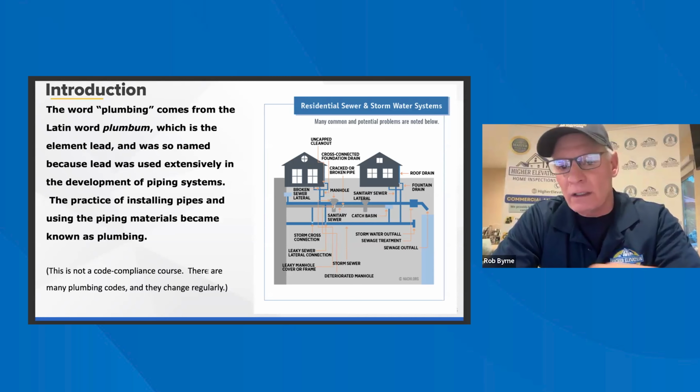And you can tell because one section is going to have air and the other section is going to have the water. You tap on it and you'll hear a distinct difference between the two. The expansion tank provides space for the water to expand as it's heating and keeps the water pressure within the normal operating range while the boiler is working. So you can always tap it and listen to the sound. If they both don't have that hollowness to it, then that means they're full and it could create a problem.